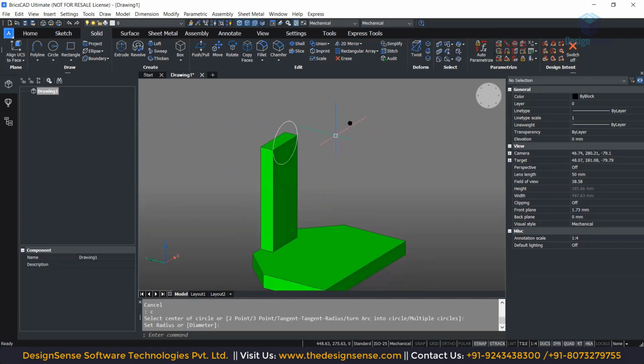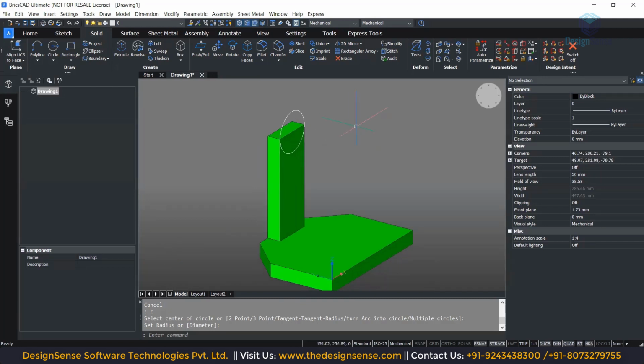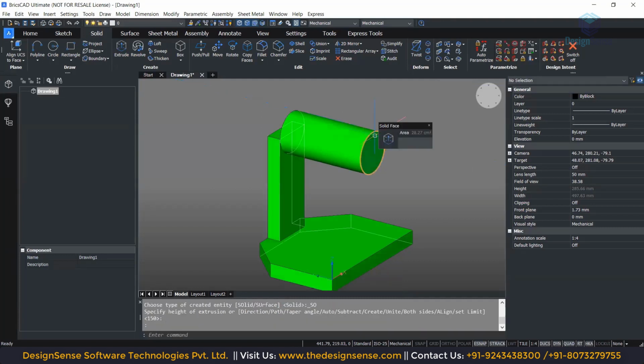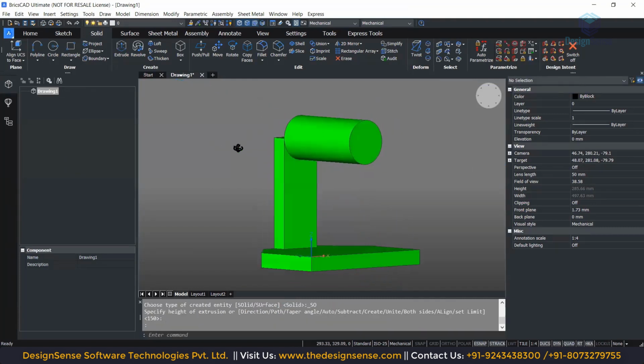Both work well. Now, the next step is extruding the circular profile by a distance of 130 mm perpendicularly away from the vertical stand. So this is extruding again, but perpendicularly away. Okay, so just move your direction away from the vertical stand and simply enter the dimension, 130, and hit enter. Should be able to extrude it.